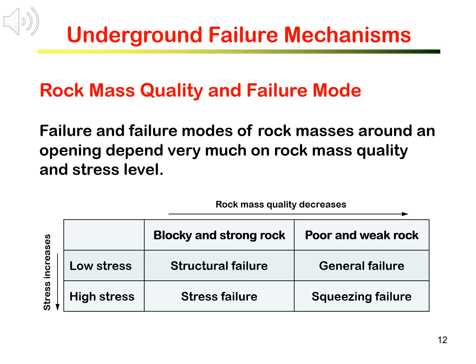Let us recap what we have learned on failure mechanisms. We now know that the two factors causing underground excavation failure are rock mass quality and the stress level.